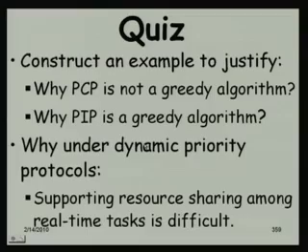Okay. Now, let us proceed from that point. So, in a dynamic system isn't there any resource sharing at all? It is very difficult. See, if the system is loaded, right. If a task rarely executes, then that task may not cause inversions to other tasks. Now, let us say that task runs frequently and it is also using critical resources, it can cause inversions to other tasks under EDF.